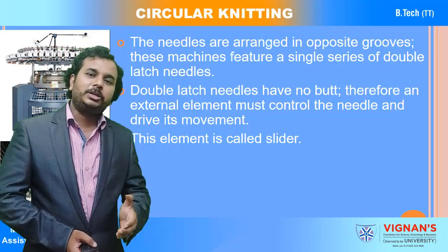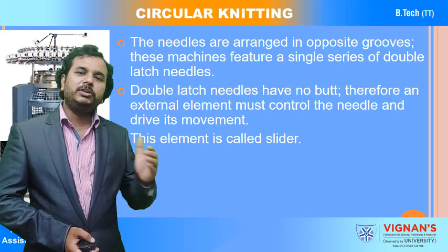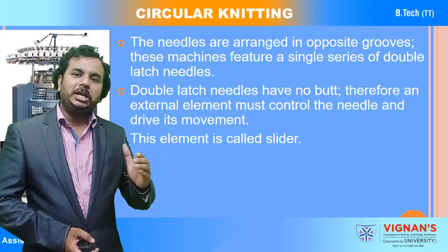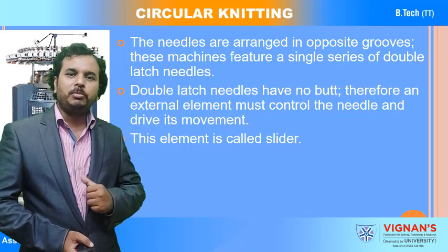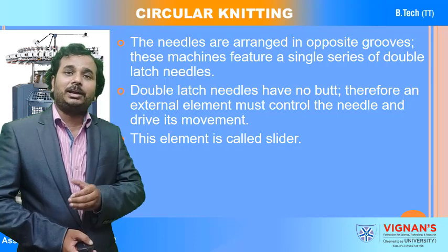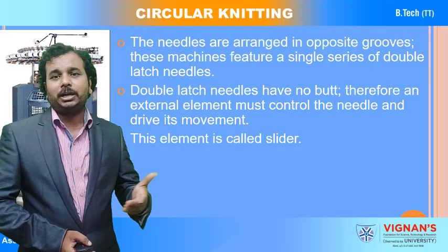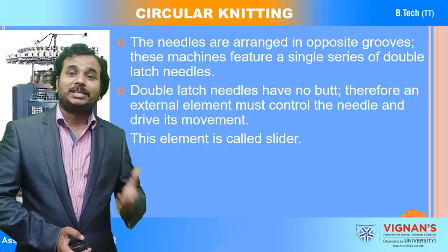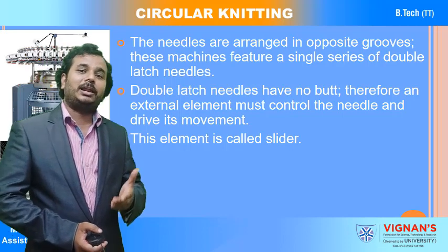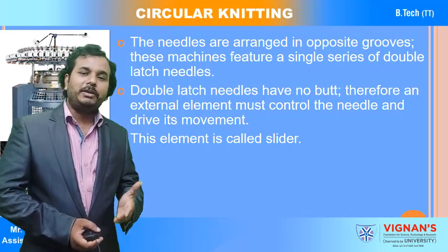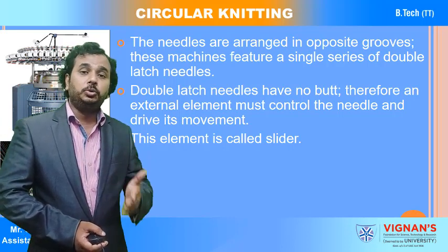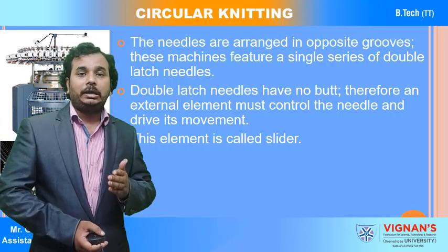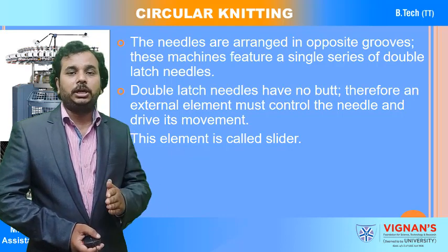For the formation of loops between the two cylinders, the needle has to move up and down, so an external drive is required. That external drive is called the slider. There is a slider which is used to operate the needles in between the two cylinders.